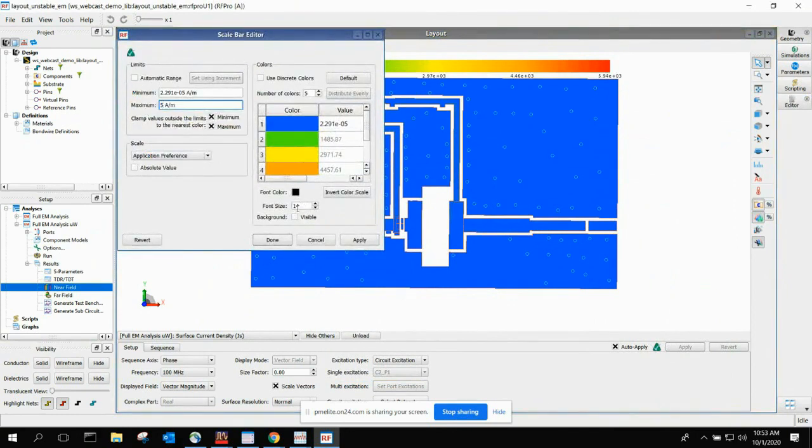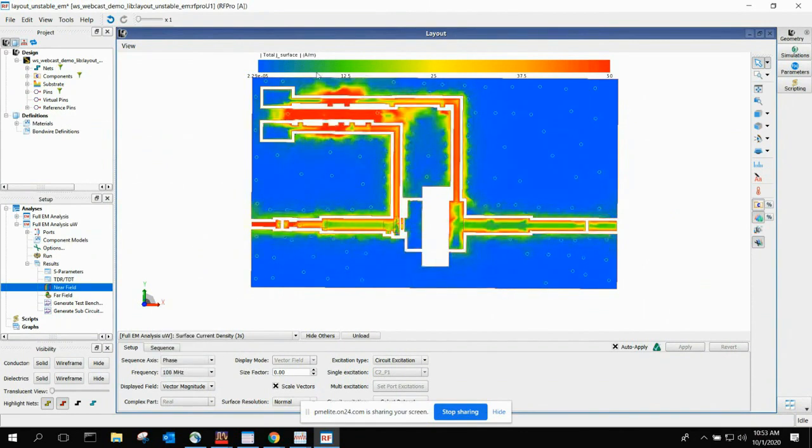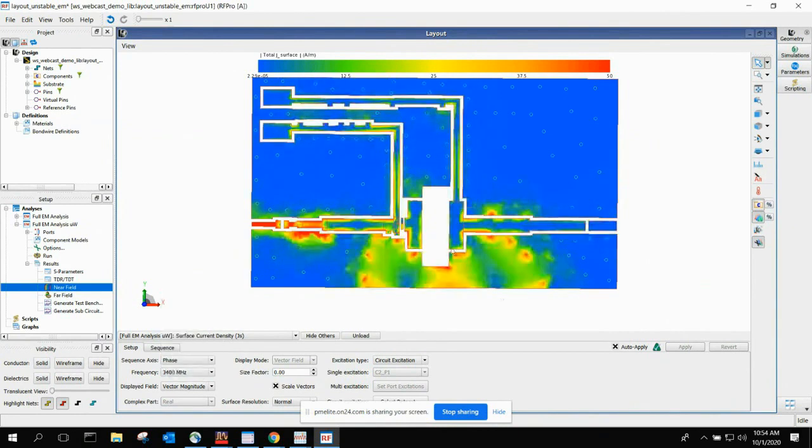So I'm down here. Well, first of all, let's go up to the transmit frequency. So this is 1 gigahertz. So the transmit frequency, these are DC terms. They're blocking the signal. And here's the AC, and everything is going through the amplifier. So that's cool. Down at low frequencies, remember there was a low frequency oscillation. We saw it in our Kurokawa oscillation condition. You can see where the board lights up. This is actually the bias line ground. So my bypassing ground signals coupling through here. If I need to separate these two bias lines from each other, and that's going to improve the stability of the system. Go up above the transmit frequency.